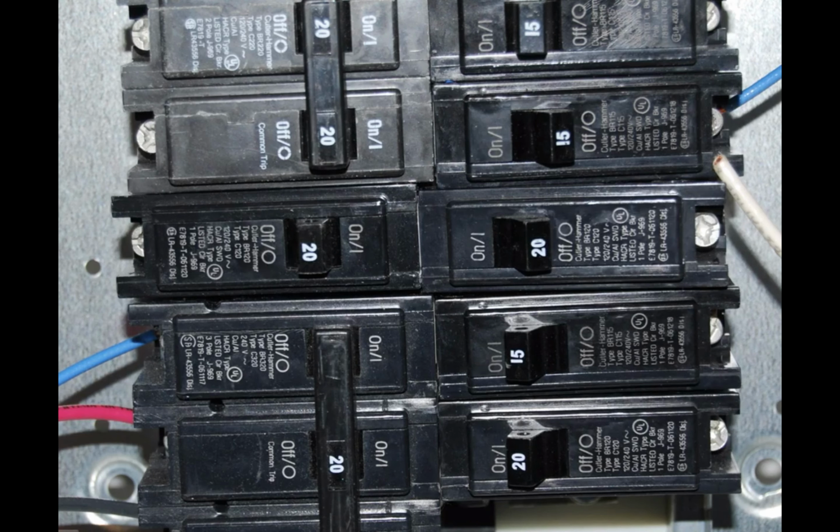As you can see, except for one, all are on. One has been tripped, the 15 amp breaker, second down from the right. They're either working on something down the line from there, and that's one of the best places to safe off if you're working on something. So you find the line that the outlet or the lighting that you're working on is connected to, and you trip it right at the breaker, and that prevents any voltage or current from going through the wiring down the line from there. As soon as you're done working, you flip that back on so that you start getting the flow of current back through the wiring.